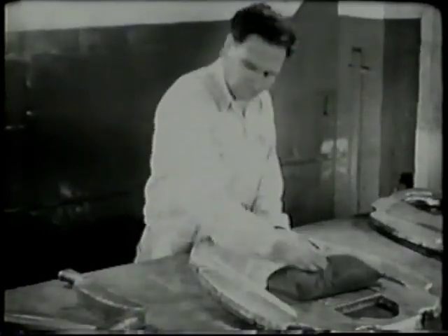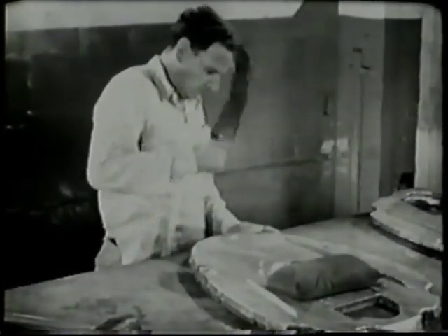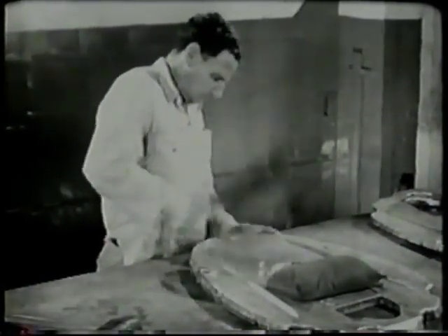Both quench tank and spray booth operations may cause distortion of the alloy parts, resulting from the swift drop in temperature. Hand hammering of the parts may be employed at this point to remove much of the warping caused by the quick quench.